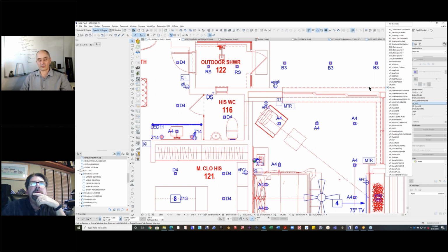And it's really been able to allow me to, this was too involved, maybe, but for example, if you wanted to do a color site plan, you could use a graphic override to allow you to do a color site plan, but then on the next paper, turn off all those colors and just have a black and white site plan, right? Without changing any layers.